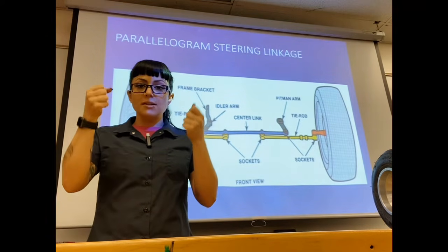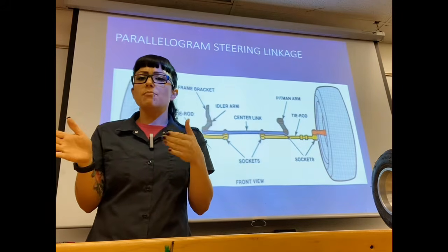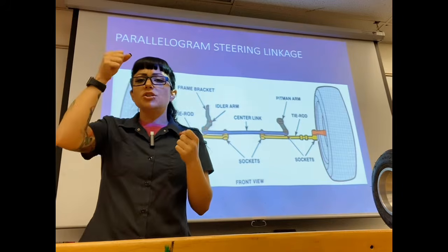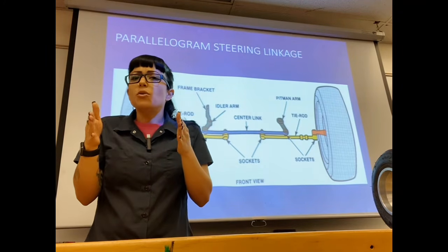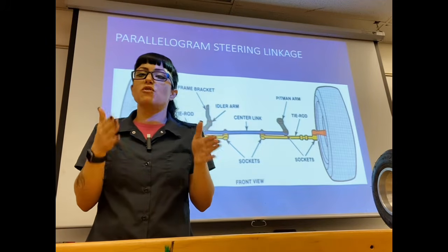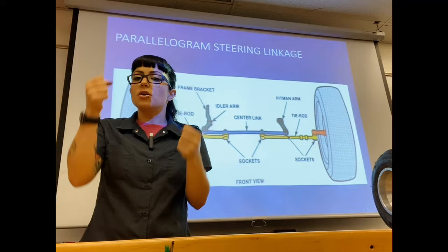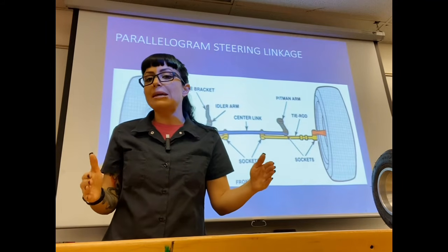One person's going to be inside the vehicle, moving the steering wheel back and forth. You're not trying to move the actual wheels. You're just trying to turn the steering wheel in one direction until the wheels are about to move, and then back in the other direction until the wheels are about to move but don't really move. So you end up turning the steering wheel back and forth like this, and while the wheels aren't doing anything,